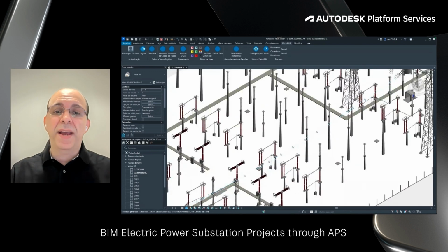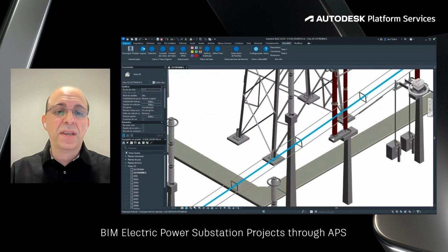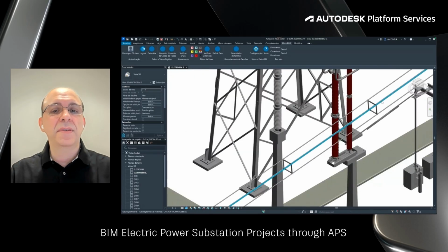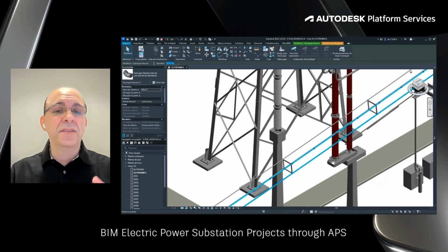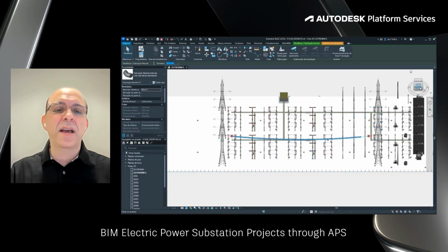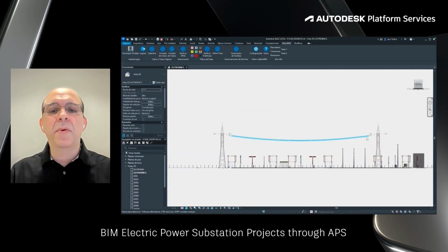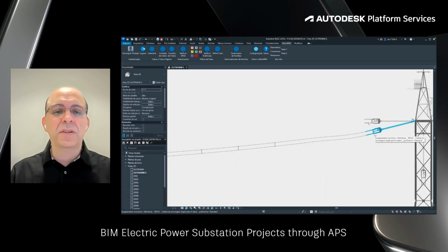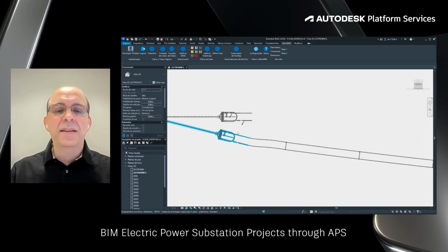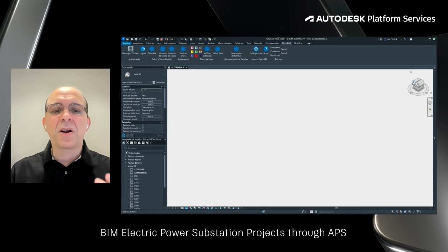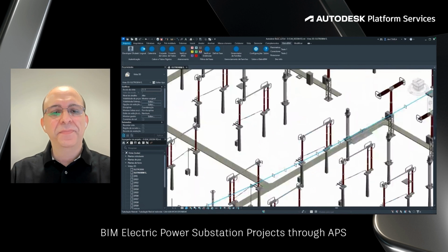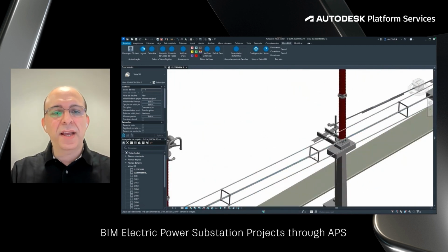And thinking about existing substations, they need to scan a point cloud, but they need to trace those cables in a real-time scenario, so they can see if the situation today is matching what is expected in the design process. And you can see here how many points are traced. You can see also the spacers, and it's a long span, right? And you can, again, see how complex that would be if you needed to do it manually, okay? So moving to the next one.